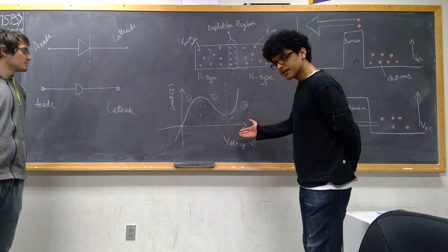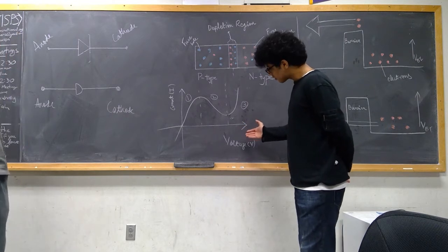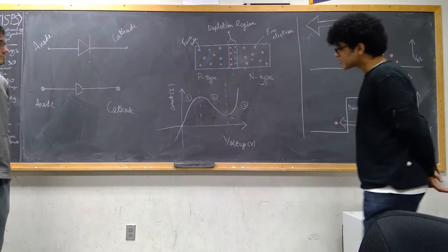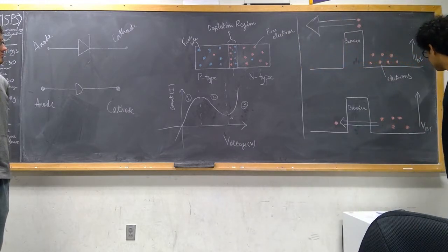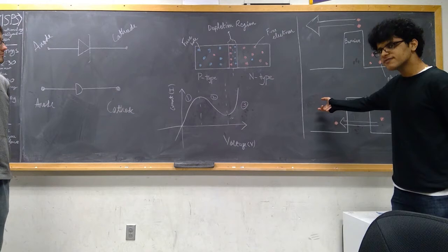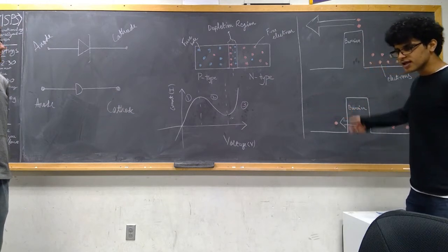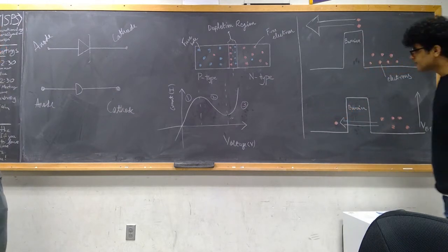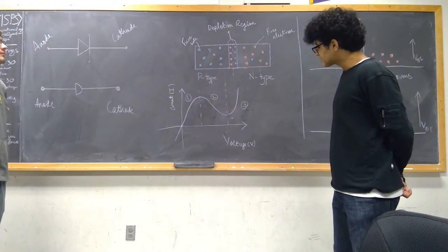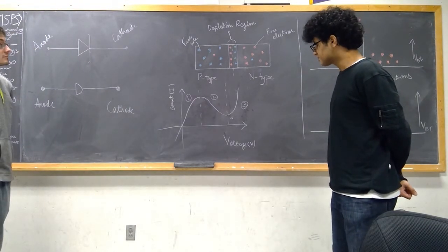And if we increase the voltage more after that, the current will start to increase. This current is due to the fact that now electrons on the n side of the semiconductor actually have more energy than the barrier and can pass over it very easily and don't need to tunnel. In this region of the IV curve, the tunneling diode displays the characteristics of a normal PN junction.